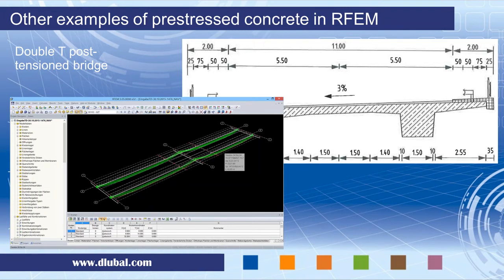The slab had zero stiffness in the longitudinal direction, because in the longitudinal direction we had these beams, but it has some stiffness in the transverse direction to make sure that those beams share the load applied only on one of them. So that was the model.